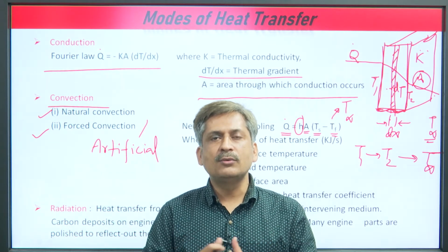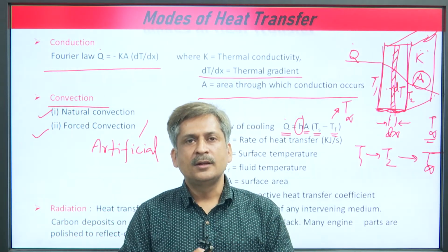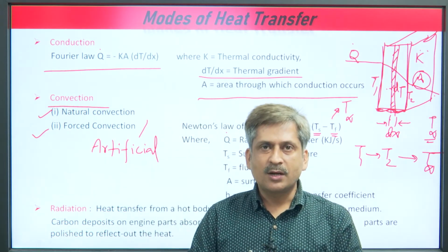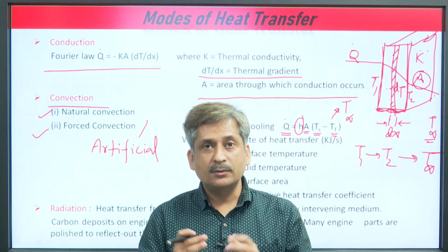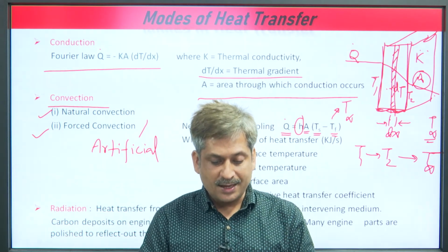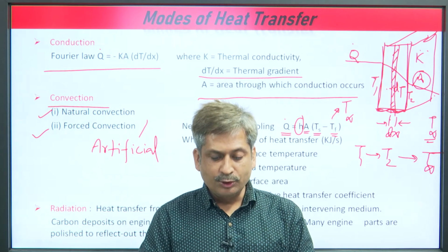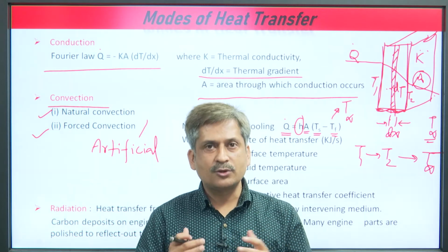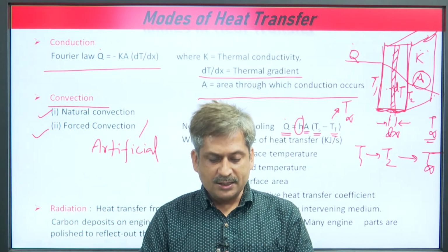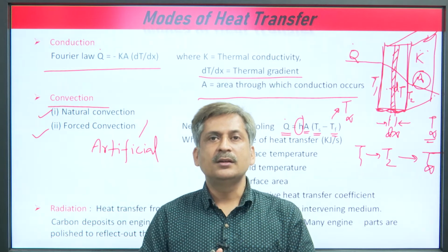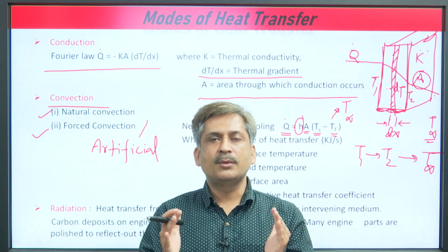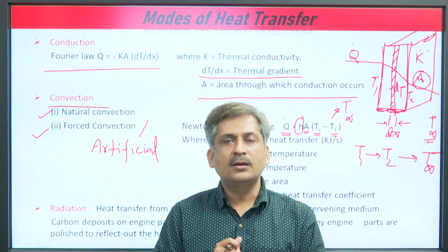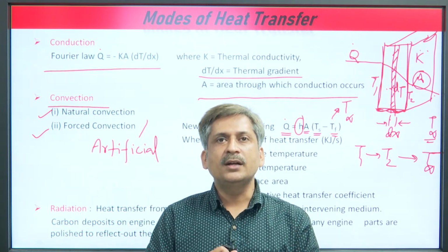That heat you are feeling is because of radiation, and it is also important because the carbon deposits from the combustion of the fuel on the engine parts absorb heat due to being black. These carbon deposits act as a black body. So, they absorb the heat, and many engine parts are polished to reflect out the heat. So, engine structure, material, roughness, and polishing are a very important part of engine design.